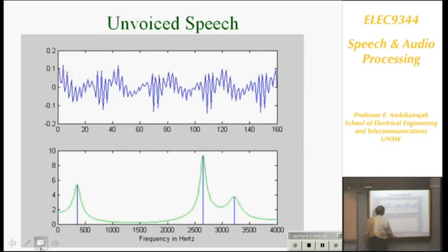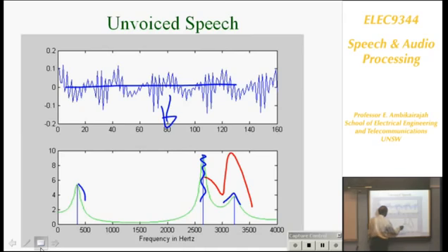Here is an unvoiced sound. It's important to know there's no pattern. It's a very noisy sound. If I take the Fourier transform of that, you can see in this particular case, this is higher, and this is lower, and this is lower, like higher. In reality, if it's a perfect unvoiced sound, you will find this is higher, and this is lower, and then this is very much lower. That would be the correct one. But I just picked a frame which is not really unvoiced and not really voiced, but kind of in between, which shows that particular pattern. It can confuse sometimes.